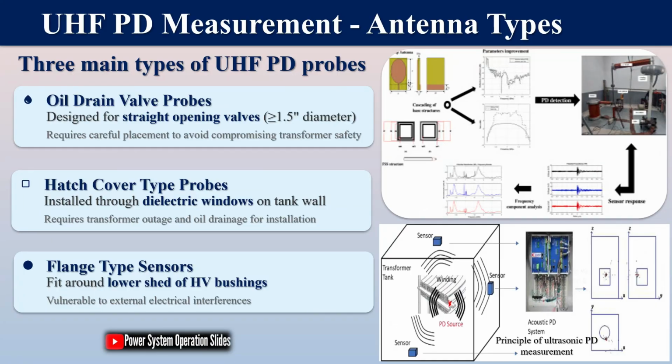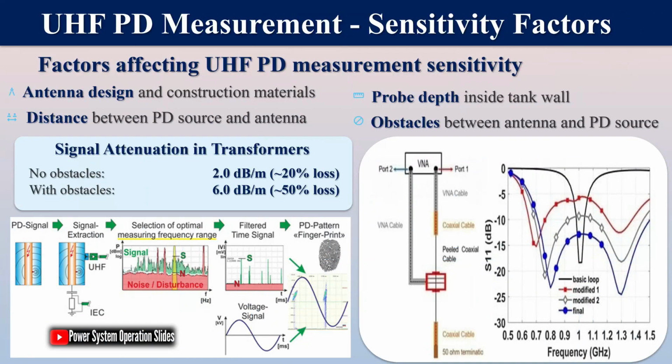The conventional method allows precise calibration but requires a sufficiently high signal-to-noise ratio (SNR) in the measurement circuit to easily resolve the PD signal. The primary advantages of conventional PD measurements include their ability to be precisely calibrated against known references, providing standardized results that can be compared across different laboratories and against pass-fail criteria, typically 500 pC for factory acceptance. Additionally, phase-resolved PD patterns are widely available for different discharge defects and high-voltage components, enabling more accurate diagnosis